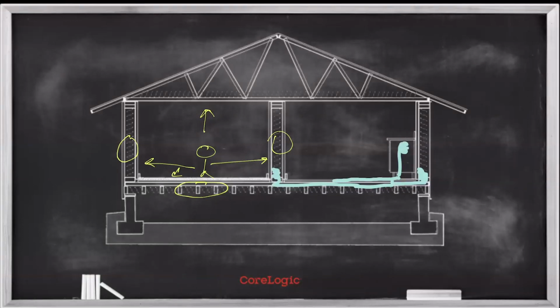Don't look at the wall and call it a wall. What you're looking at is paint, right? What's behind that? Well, what's behind that is drywall. Well, what's behind that? What's it holding on to? What is it attached to? It's attached to studs. What's between the studs? Is it air? Is it insulation? You've got to think of each one of those components and ensure that you've checked the box that you know what those components are. Only then can I establish the appropriate instrumentation to verify whether or not the moisture has actually affected those materials, right?